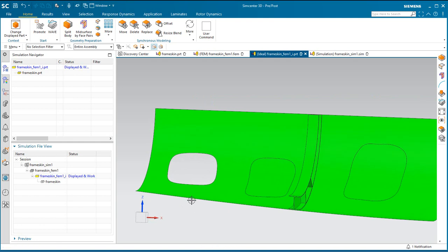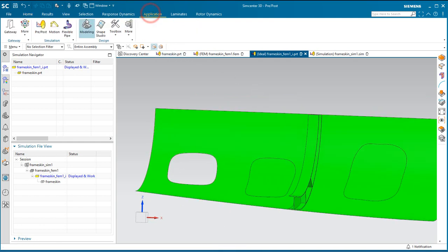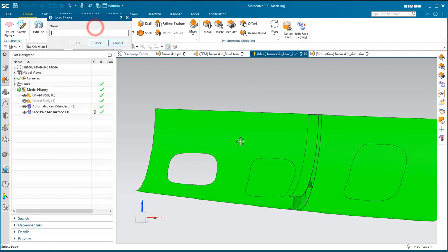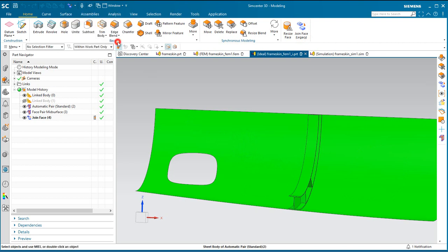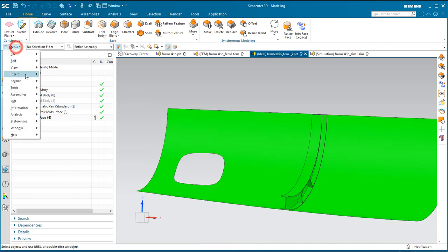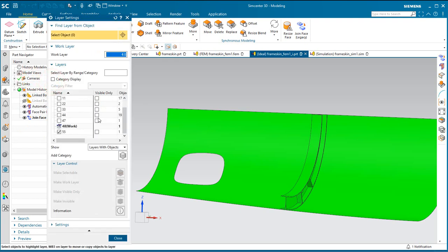We have a couple of different variable thickness regions in the skin, which for our coarse grid model is not important. So I'll go ahead and remove those different thickness regions. However, we do want to maintain the different thicknesses in those areas, and we'll still be able to do that.